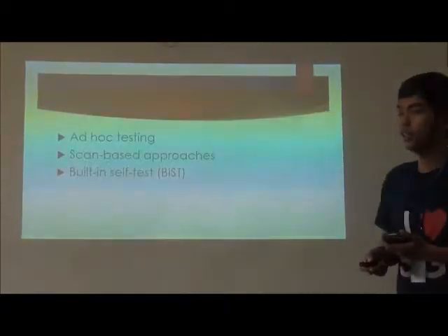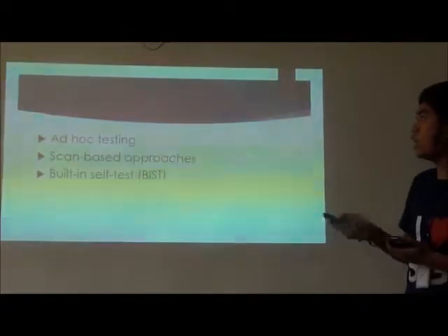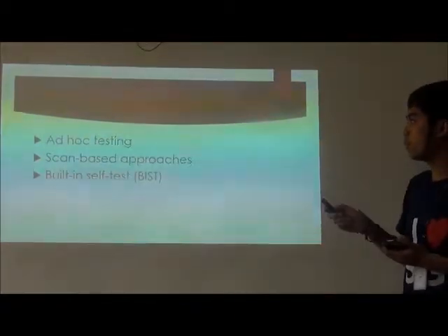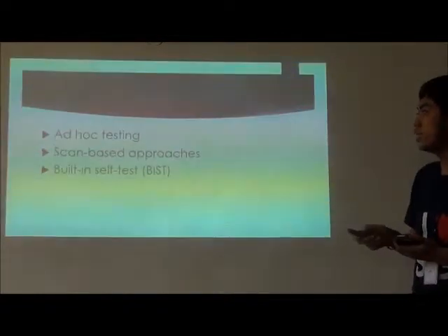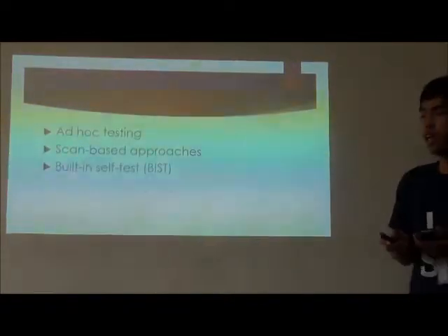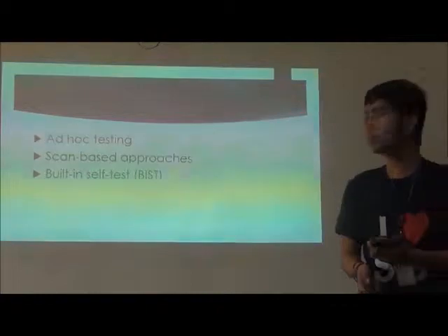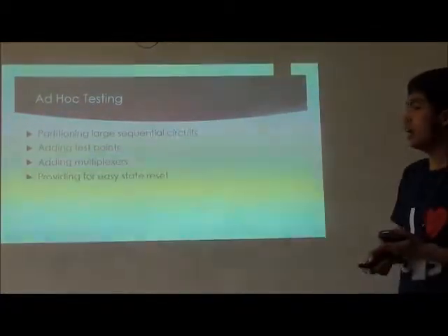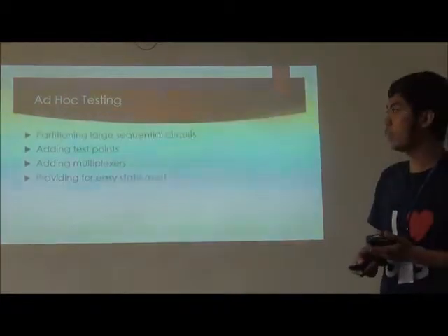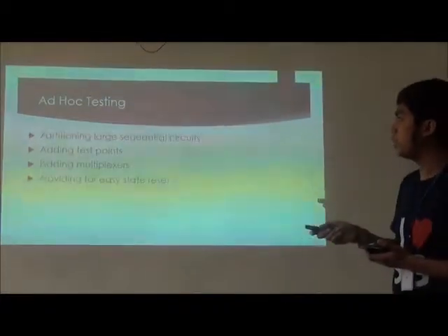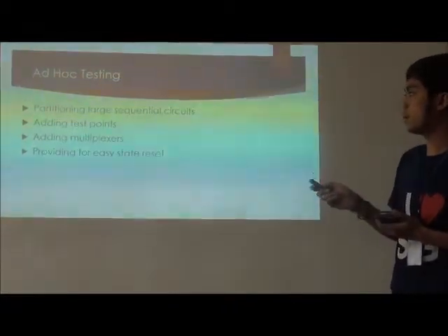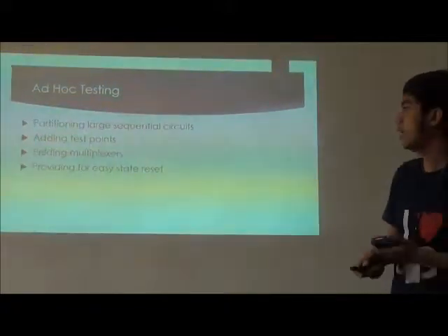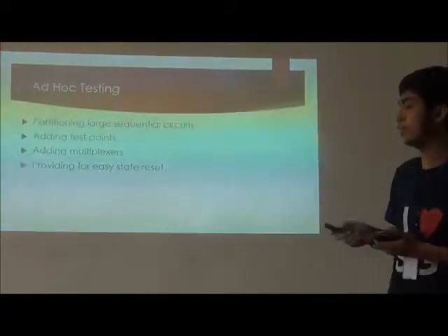So we have this part: ad hoc testing, scan-based approaches, and built-in self-test, or BIST. Ad hoc testing. In ad hoc testing, we have four categories. We have partitioning large sequential circuits, adding test points, adding multiplexers, and lastly, providing easy state reset.